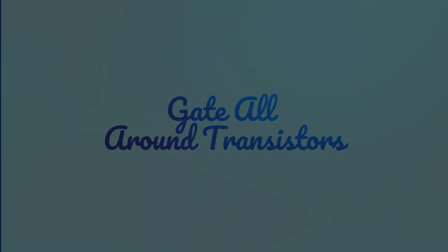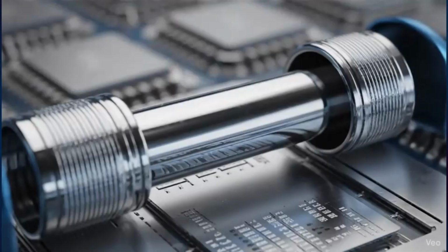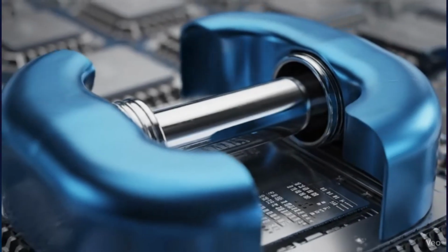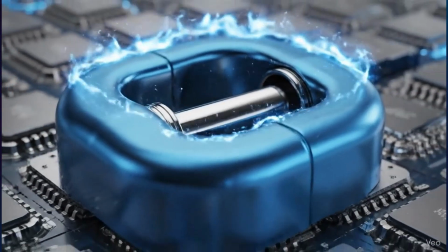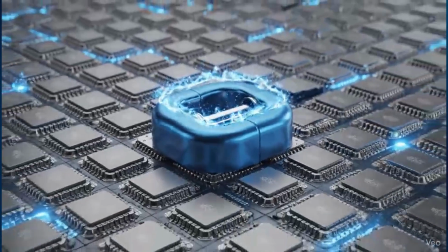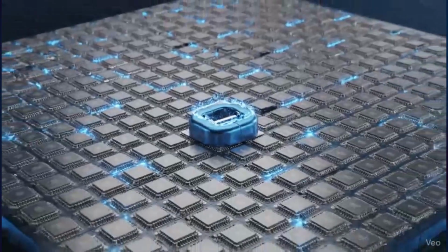Gate all around (GAA) transistors take this a step further. The gate fully surrounds the channel, like wrapping a pipe, offering even better electrostatic control and minimizing short channel effects. This architecture is being adopted in nodes below 3 nanometers.